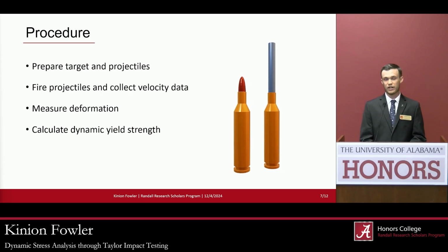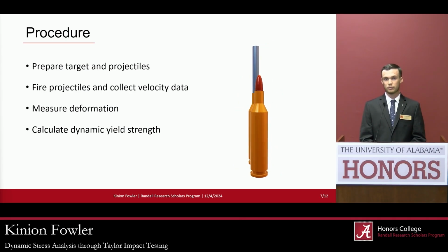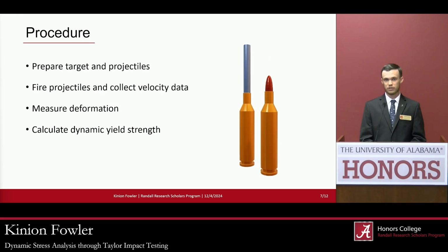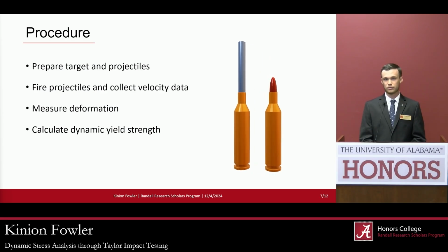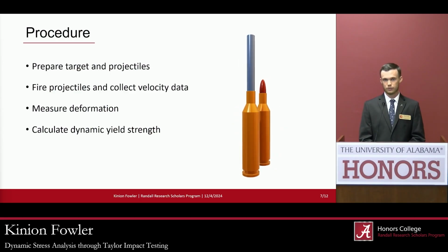Then we perform our actual testing where we fire them and measure their velocity. We measure the deformation after impact using a laser micrometer, and finally we're able to use those measurements we took to calculate the yield strength of the material.